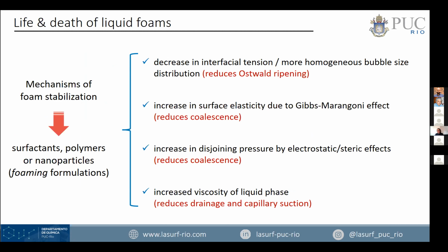They increase surface elasticity, which is the major stabilization mechanism for these foams due to the Gibbs-Marangoni effect. They increase the disjoining pressure, especially when you have charges in these materials, and then you can have electrostatic effects, or in the case of polymers and some nanoparticles, steric effects as well. And they increase the viscosity of the liquid phase, because it can reduce drainage and capillary suction.